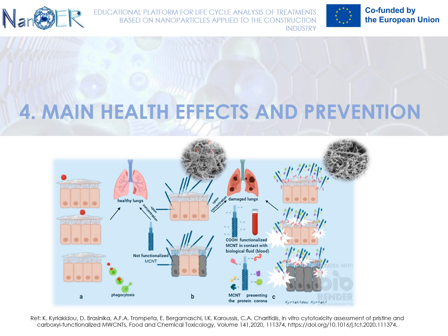The use of CNTs in the construction sector could cause serious lung diseases in the workers and staff who get exposed to them. Studies that have been made on animals have shown that CNTs have the potential to harm the respiratory system of living beings by giving rise to severe inflammatory and fibrotic reactions if they reach the lung. According to recent advances, these reactions could lead to the genesis of a tumor with an increasing rate. The overall estimation of pulmonary toxicity is relevant to the dose of CNTs inside the lungs.